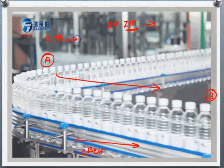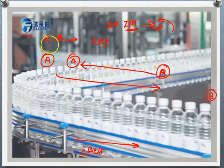What will happen if this phase sequence is changed, if by mistake the phase sequence is reversed, that means it now becomes RBY? Then the motor will rotate not in this direction but opposite to that. That means the direction of the motor is now reversed. So the conveyor belt will also reverse its direction, from B to A. Now the conveyor belt is moving from B to A. What will happen? The filling and capping of the bottles cannot be done effectively. Okay, this is the problem with reversing the phase sequence. So always the normal phase sequence RYB should be maintained.